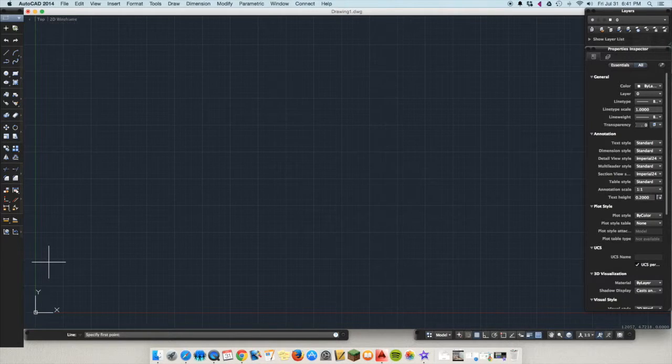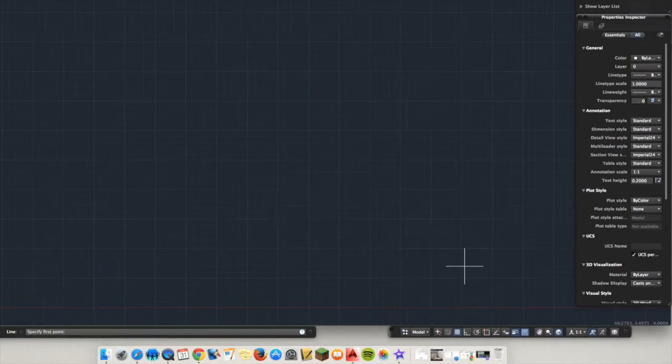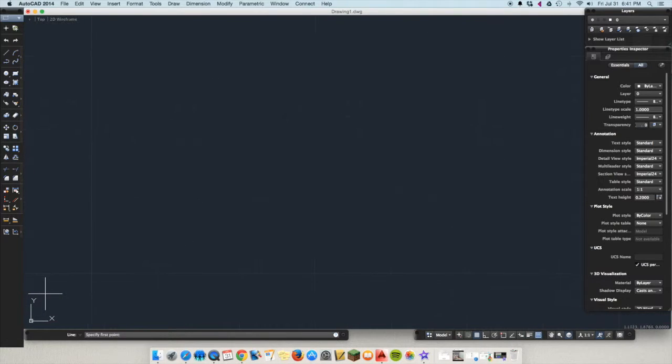Now, one thing I want you to know about this grid, and I don't know if you'll be able to see it as well as I can see it, but down here on the bottom right, as I move, you will see the X and the Y values, the absolute coordinates, showing up as I move the cursor around. Something for you to know as I zoom in here on the grid is that you might think of these little tiny grid squares as one, but the way the program is set up currently, they are considered half units. So if I were going to start here and go to here, that's only 0.5, and same thing going up and down. So don't get confused and think that each square is 1 by 1.